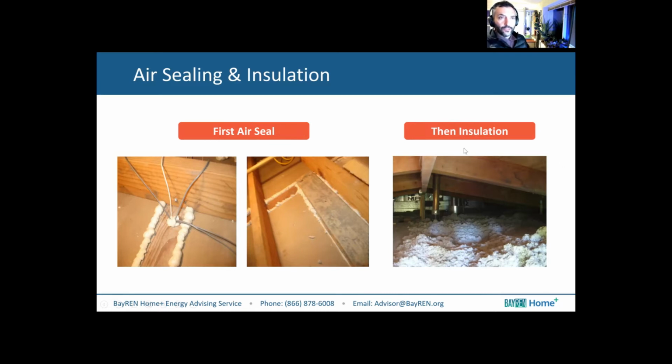First, you want to air seal, then you want to insulate. So if you have an attic space, you have knob and tube, you've got old networking cables, you've got electrical work you've been dying to do, you want to insert new recessed lighting, it's a great time to have an attic insulation company come over, or you can do it yourself. You remove all the insulation, you clear it, you hire an electrician to come in, they can see everything, they can do all your upgrades, it's cheaper that way. And then you have the insulation company come back and they air seal.